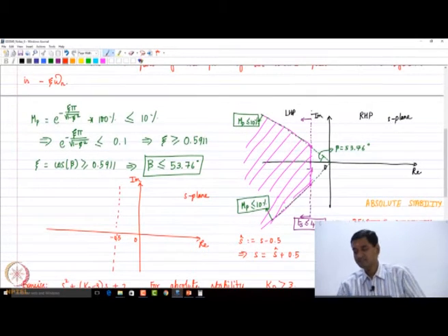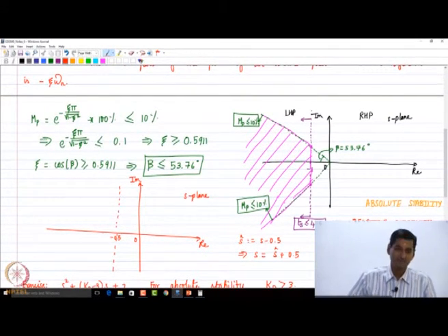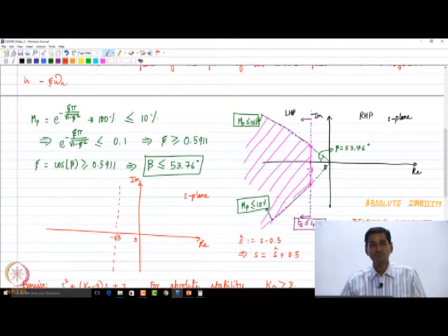See, what I mean is that, let's say you have a 10th order system, for example. So you need to design a closed loop control system which is of order 10, but still I can always say, look, I will specify performance in this manner. See, the reason is the following. We have explicit expressions for specifying performance specifications for systems of order 1 and 2, and by and large the dominant dynamics is going to be that of that order. So consequently, I can essentially create regions like this, and if I am able to place all my poles in this region, I am done.